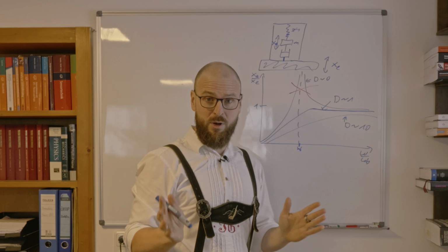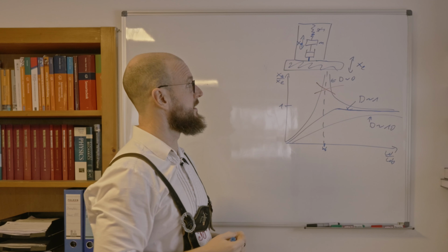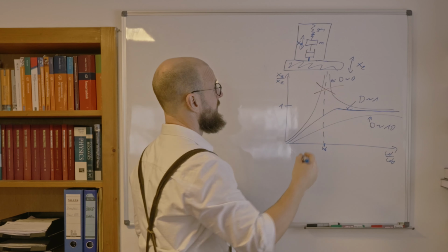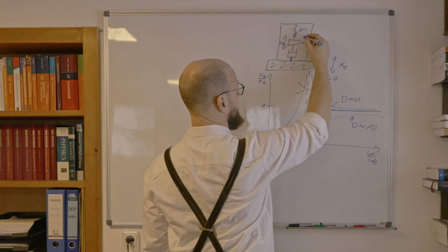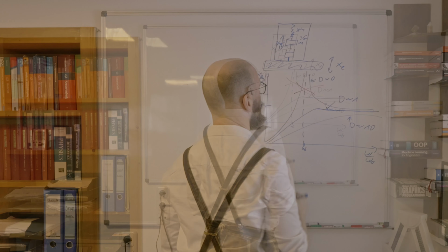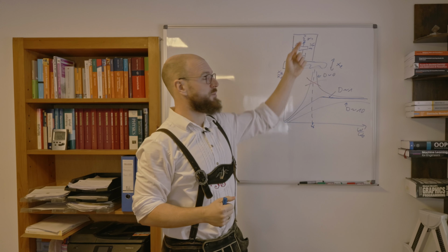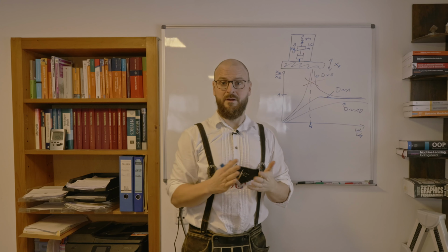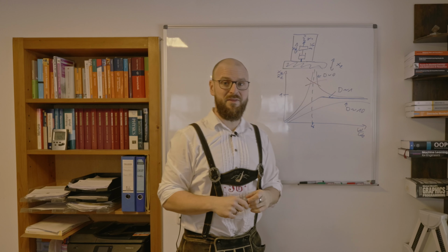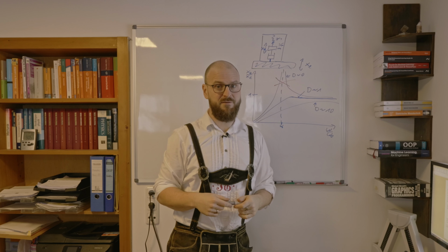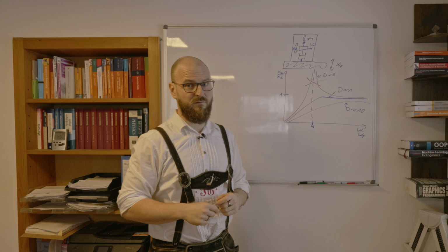Okay, now we are able to build something like an acceleration measurement device by, for example, measuring the movement over here using a strain gauge. For that, choosing a high spring constant and a high damping to get only small movements, but we can choose for that. And by that, being able to measure machine vibrations, for example. But there are other things we can use that stuff for.